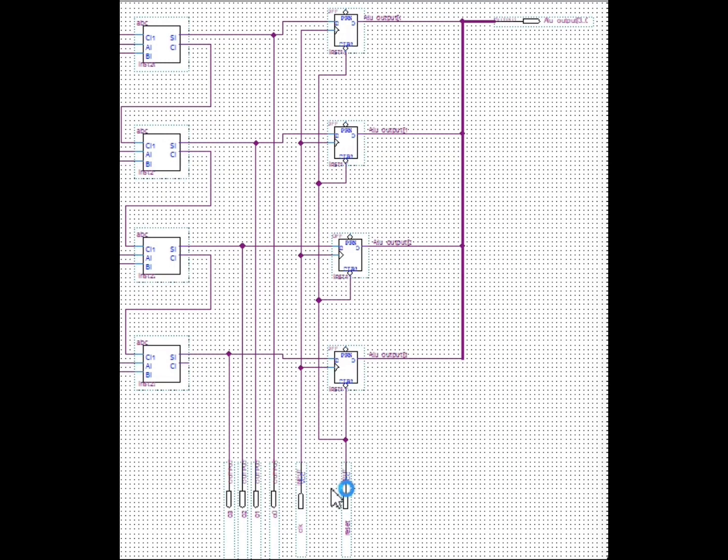When the clock signal is reaching a positive edge, the output will change to the output of the full adder, which lies on the rising edge of the clock signal. For this case, a 4-bit D flip-flop should be used and connected in parallel to share a clock signal. Each flip-flop will store 1 bit of data and will output simultaneously when a positive edge clock signal arrives.